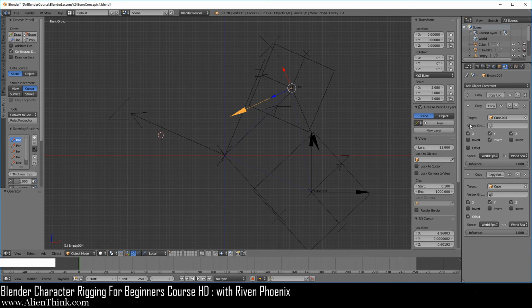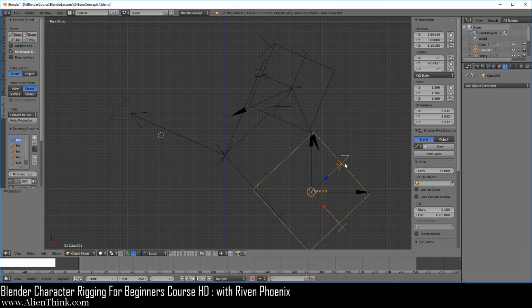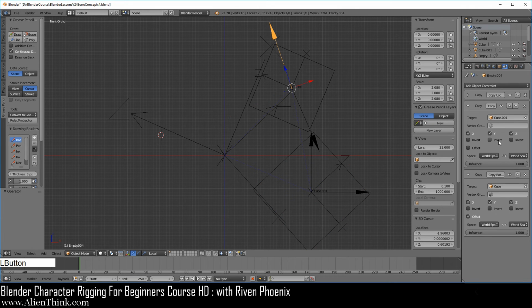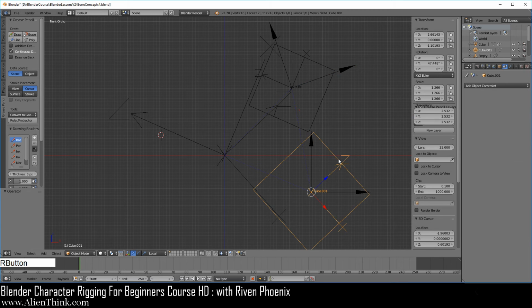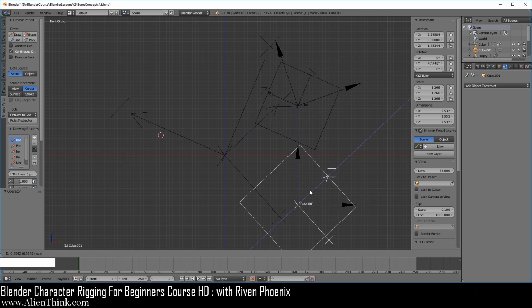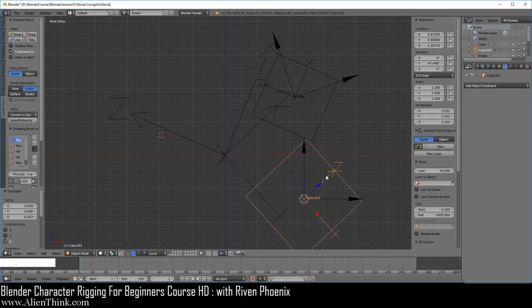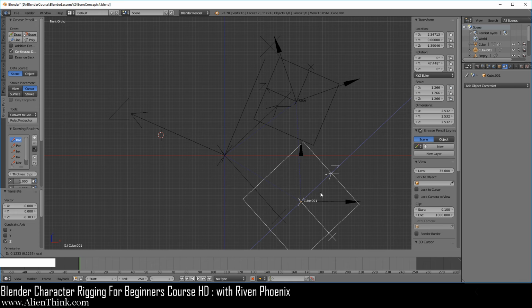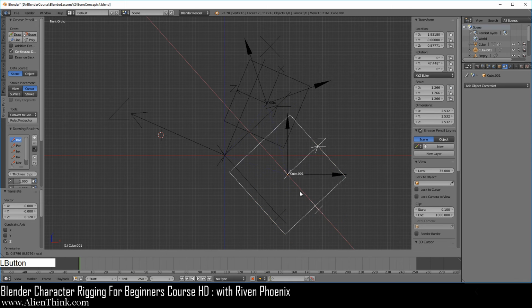So in this case, we just have to remove the invert, right? Because we only use the invert when we are evaluating this object, which exists in world space, when we're looking at it in local space. So if you go ahead and click this and just remove the invert, now you'll see that when we click on this object and actually move along its local z, you'll see how this arrow is showing how it's moving along its local z and local x.